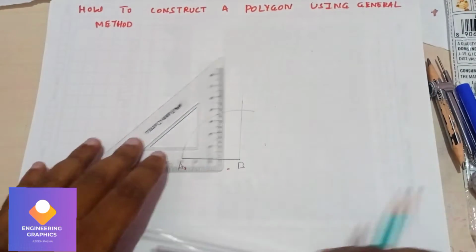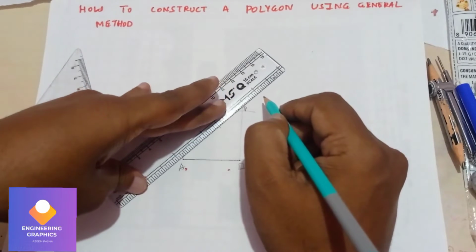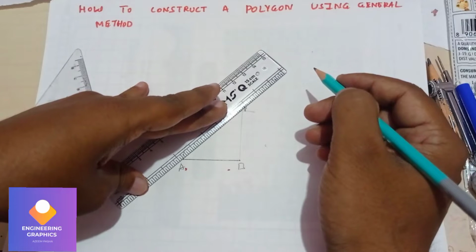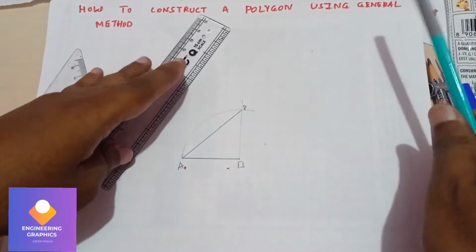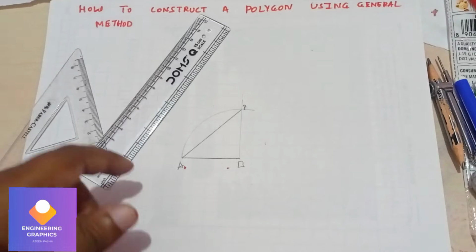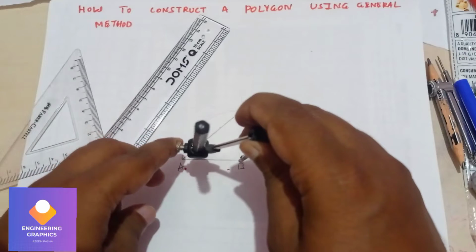Now connect this point P with this A. Now we can bisect this line AB. How to bisect this line? You just take more than half of the distance of this line AB and draw two arcs.